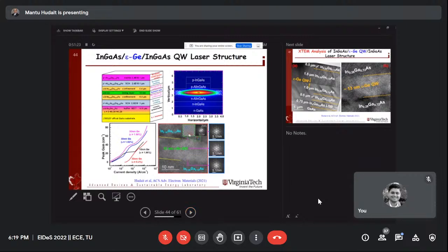See the defects here? Can you see the misfit dislocation lines? Can you see three dotted lines and through the blue line? These are the misfit dislocations of the interface. So I told my student, yeah, this is good, but you just cherry-picked some area which is looking good. I want the entire stack. Please show me the entire stack.